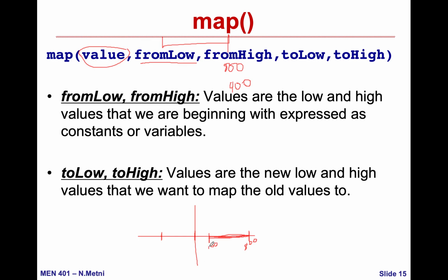What I will do is take a linear relation, so when the input is 100, my output is 100, and when it is 800, my output is 800. When the input is larger than 800, the output is constrained to 800. And when the output of the A to D converter is less than 100, the output of the function constrain will always be equal to 100.